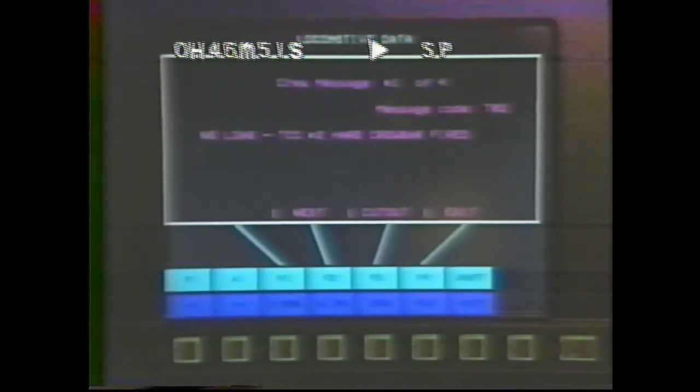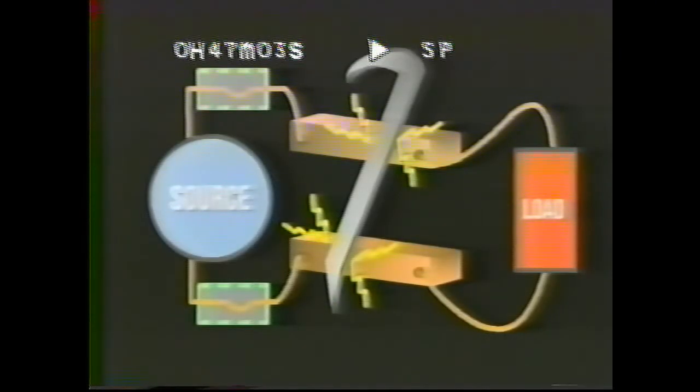In addition to providing high voltage ground protection, ground relay, the locomotive will protect electrical components during a fault by firing an electrical crowbar. Crowbar is a new term used to describe an action that removes power from the electrical components. This action is the same as with ground relays, something you're already familiar with. These are serious faults that require reporting.